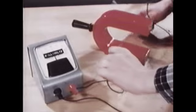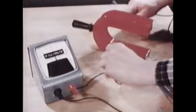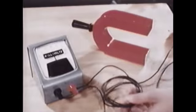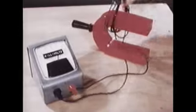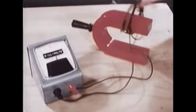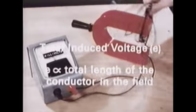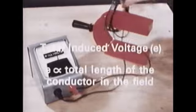To generate a usable voltage that produces current when the circuit is completed, the part of the conductor in the magnetic field should be made very long. This is accomplished by constructing coils. With a coil of several turns, other conditions being the same, we find the voltmeter deflection is greater than that for a coil with a single turn, indicating a greater voltage. This is because the total induced voltage is the sum of the induced voltages in the individual turns. Therefore, we can say the total induced voltage is directly proportional to the total length of the conductor in the magnetic field.